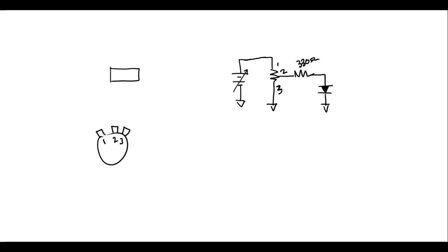So what's the maximum voltage we're gonna need? 0.75 volts, right? So over here we probably need to set this. We can set this to like 3 or 4 volts. It doesn't make a difference. We just don't want to exceed the wattage rating of the pot. And now what I can do is move this pot right here, and I can set this to get what? 0.45 volts over here, or 450 millivolts.